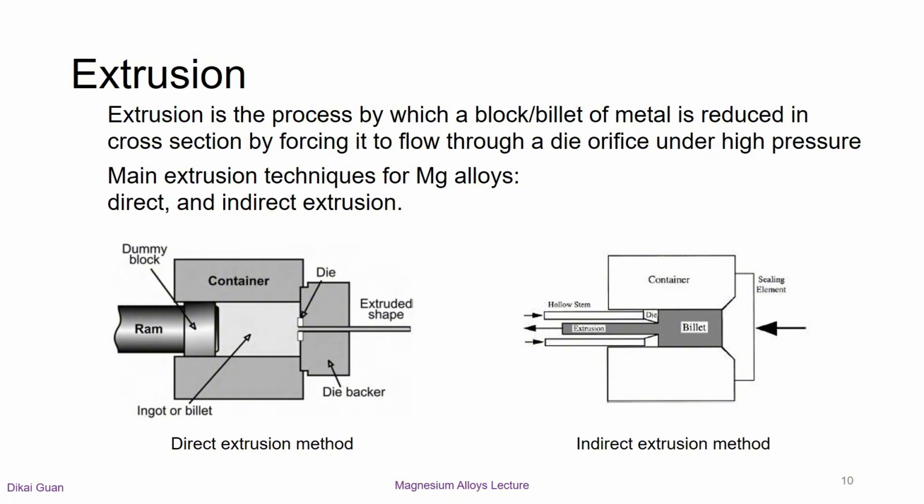Various plain and hollow shapes can be produced using the direct process. Tubes can be produced by extruding a hollow billet over a centered mandrel located inside the main ram.